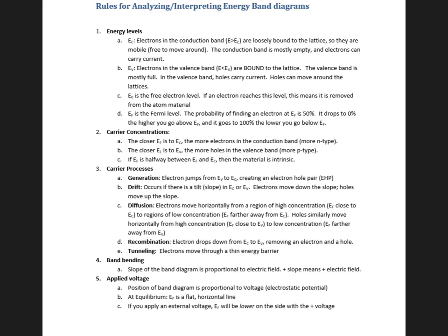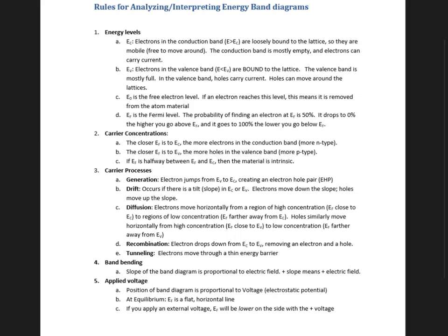And then from there we saw that we have a bend in the energy band diagram. That means we have an electric field. Then we started to think about, well, what are the carriers doing in the energy band diagram? Carriers, electrons go down the slope, holes go up the slope. They cannot overcome energy barriers, but they can get stuck in potential wells. So these were all different concepts that have been sort of summarized in here. So let's go through some of these things.